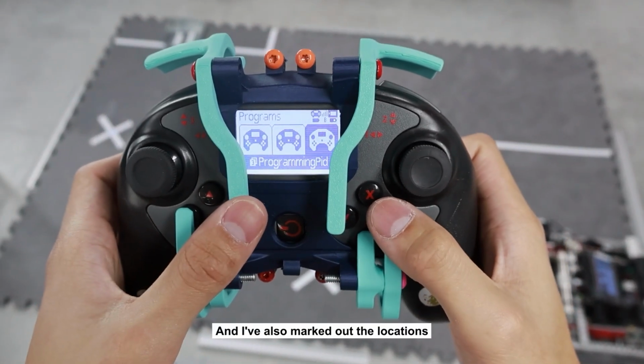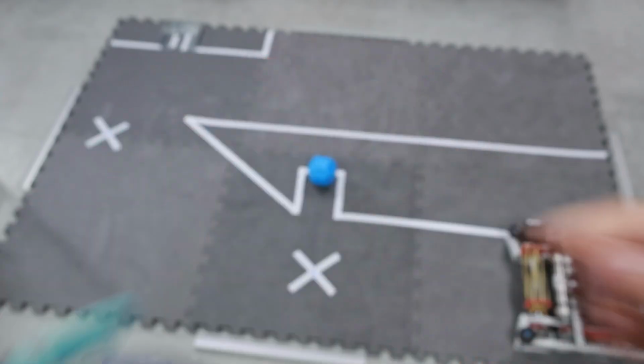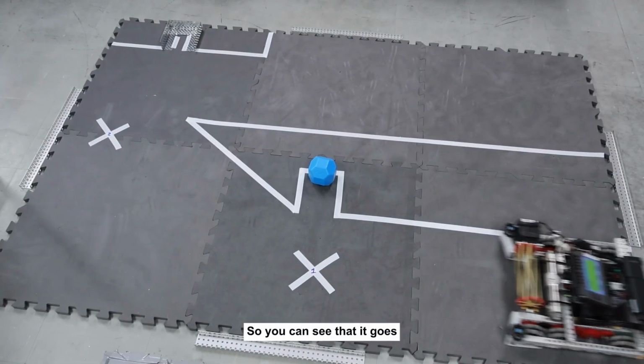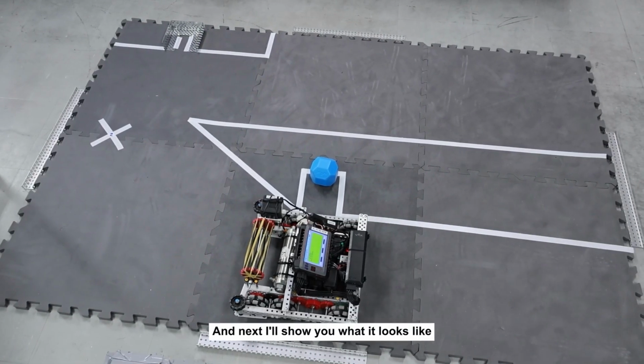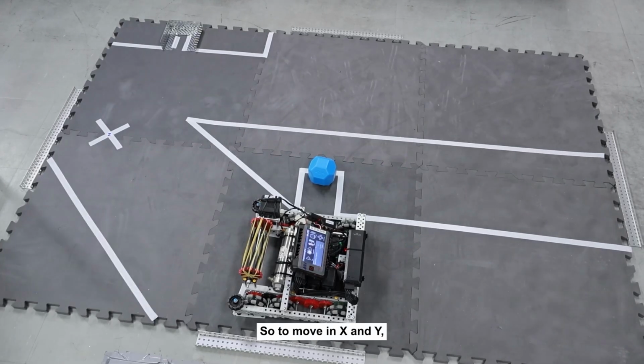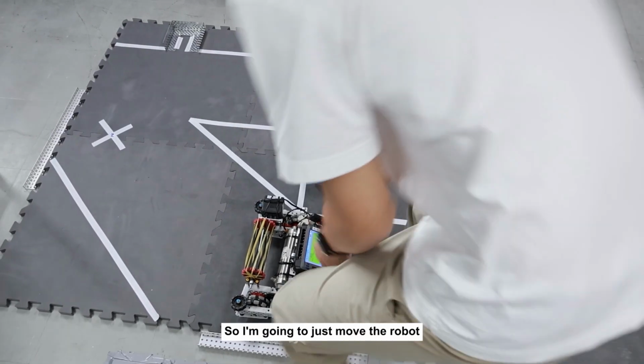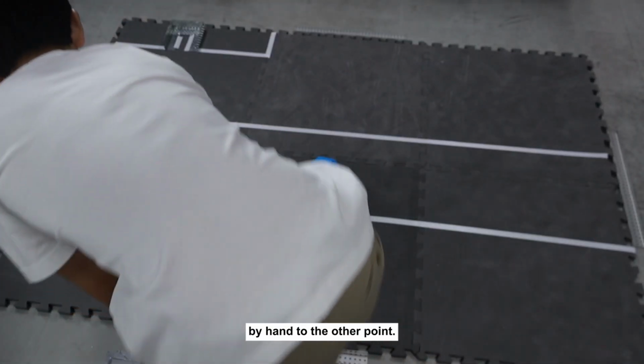I've also marked out the locations that we want it to go to in this first tutorial. You can see that it goes to the position we want, and next I'll show you what it looks like when we change X and Y. To move in X and Y, I'm going to do the exact same thing, which is run the program on the robot, and then use the coordinates that are already there to move to the other point. I'm going to just move the robot by hand to the other point.